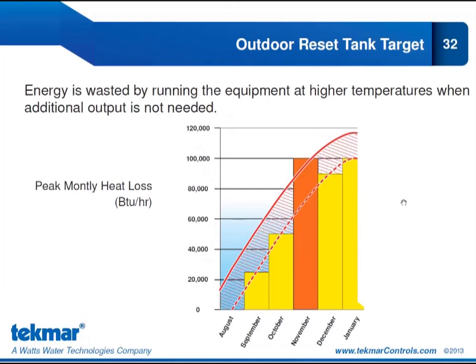What that means is my tank target is higher than it needs to be for most of the heating season, and my heat pump is likely cycling on and off to maintain a higher target temperature than is necessary. I'm having temperature swings in my zones, and I'm wasting energy and not seeing high efficiencies from my heat pump when I could.